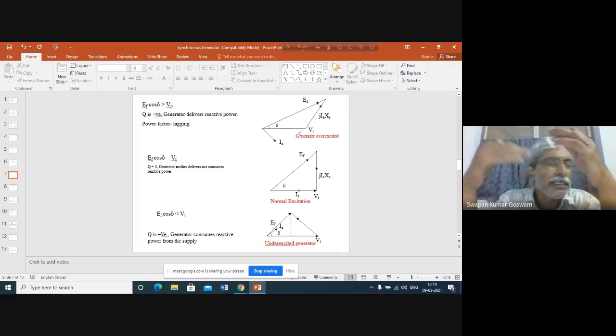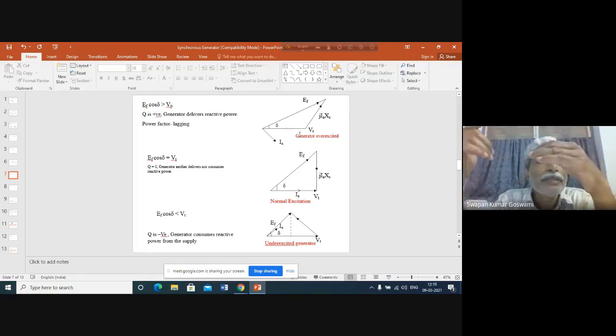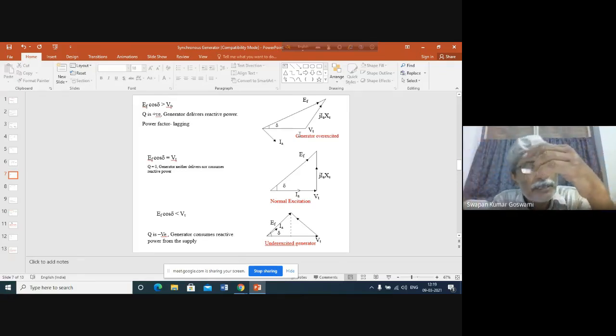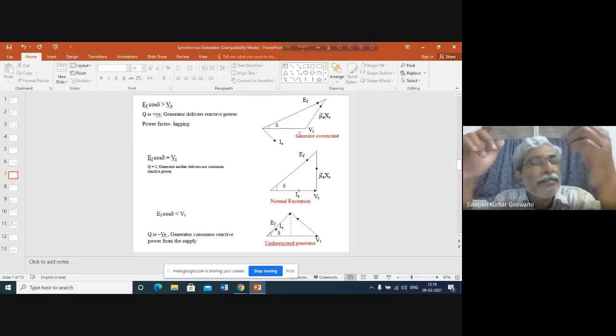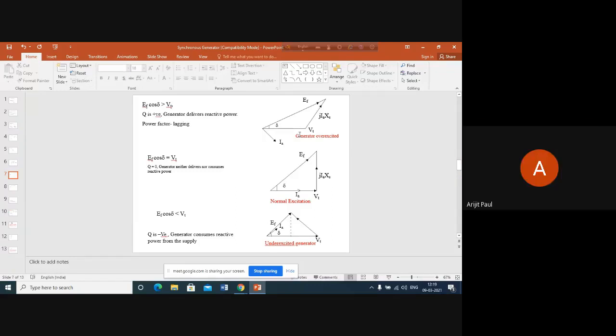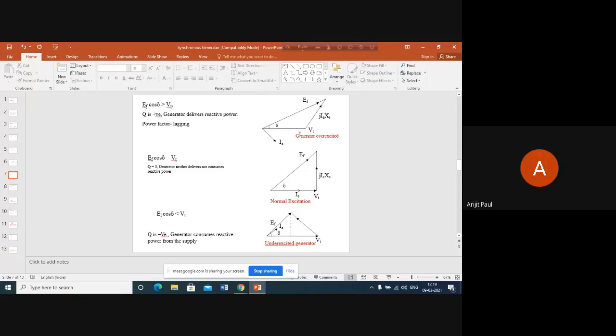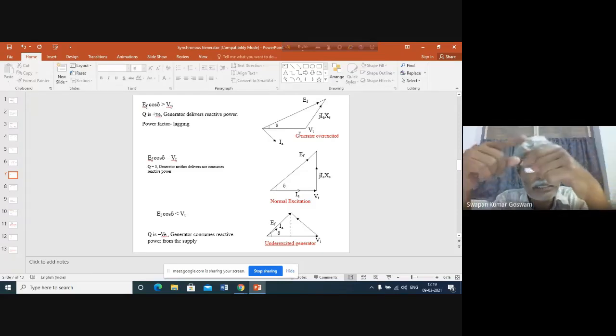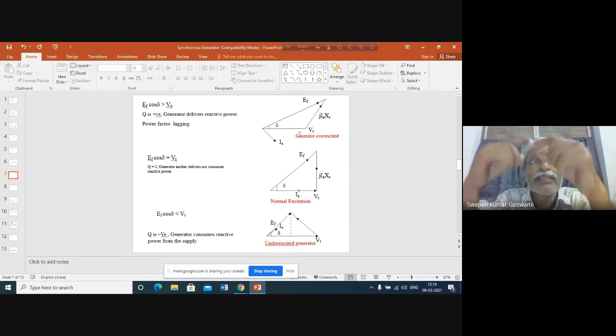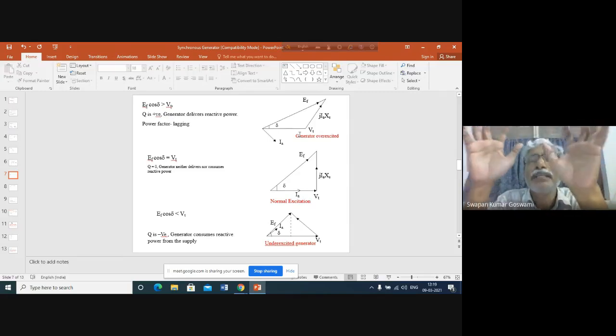At increased field current there will be increased copper loss in the field winding. I squared R loss of the field winding will also increase. As a result, there will be more heat generated in the field winding. That means the heating of the rotor.